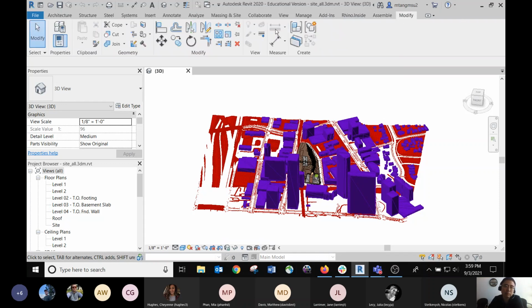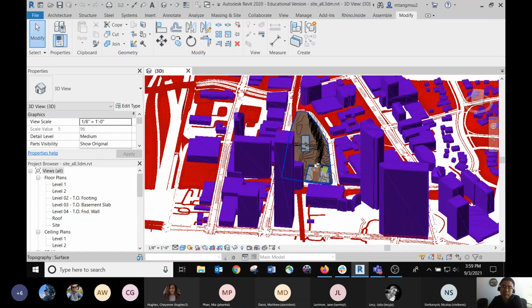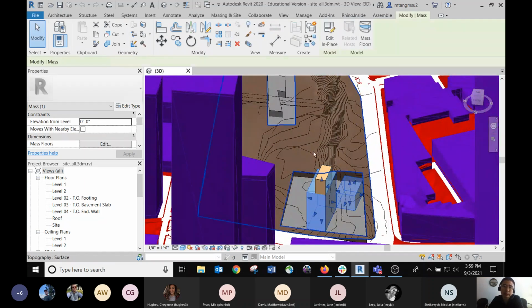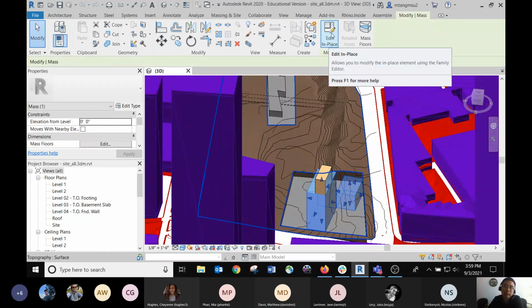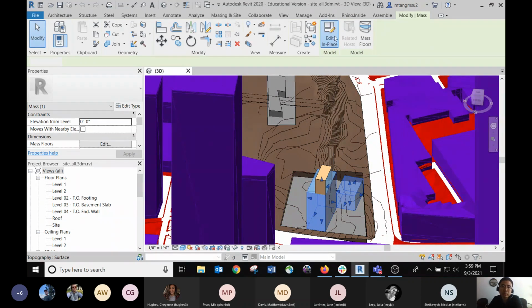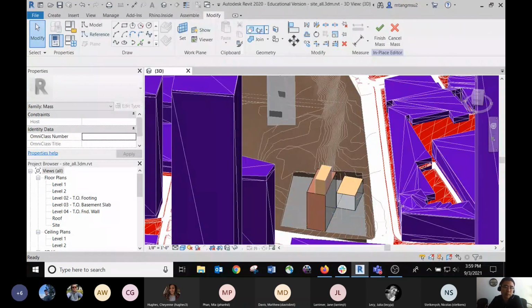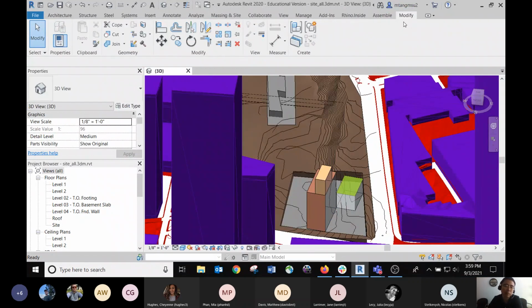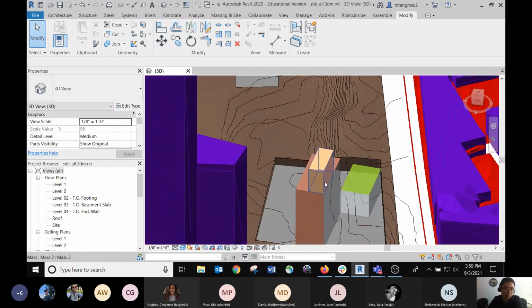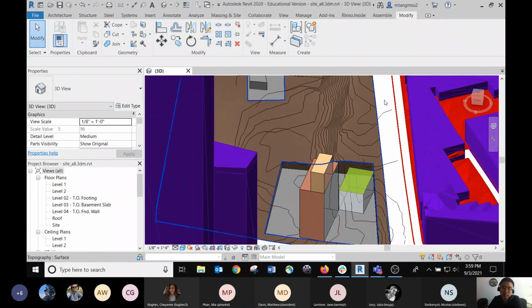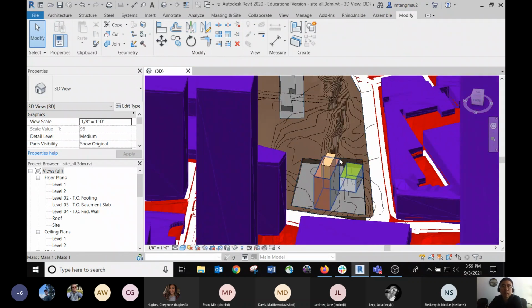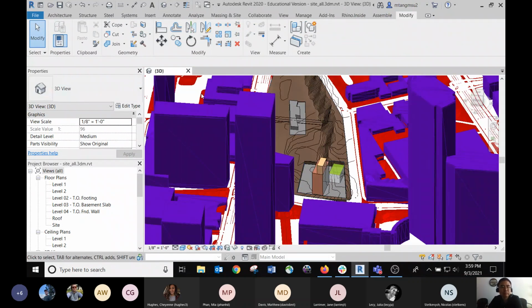Modify basically is a menu. Whenever you have, for example, a massing, if you edit it in place, it will automatically jump you into the modify submenu. If you click cancel or finish, you will get out. Then you can see other menus. So the modify tab really changes based on the current editing mode, right? It changes based on the context. All right, I think that's all right. Pretty basic stuff about the menus.